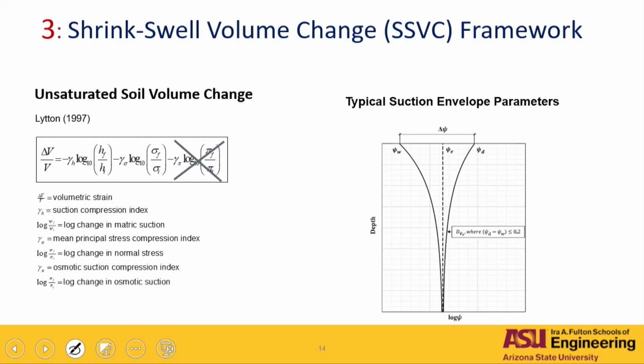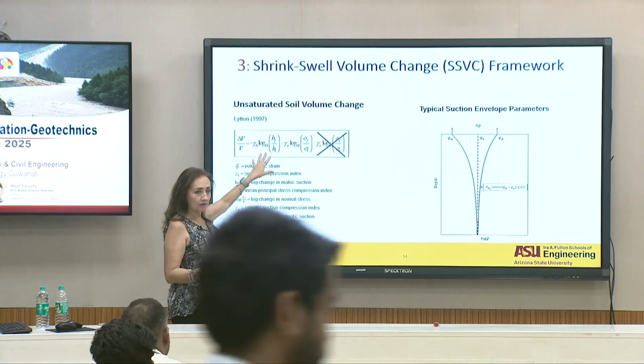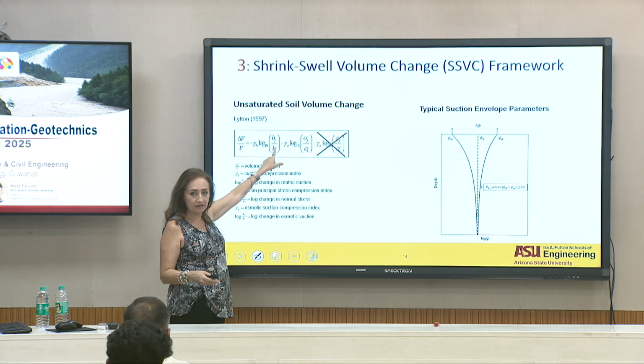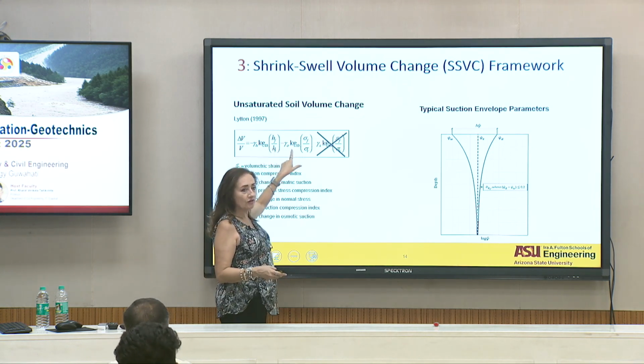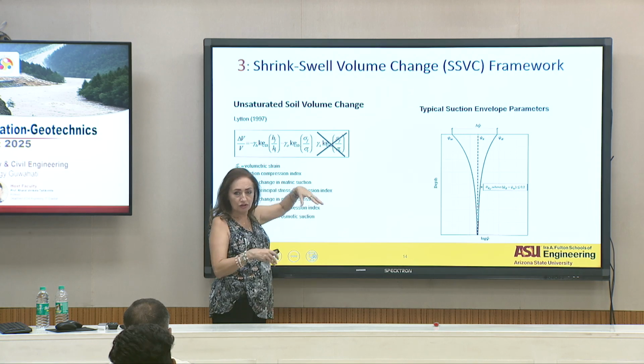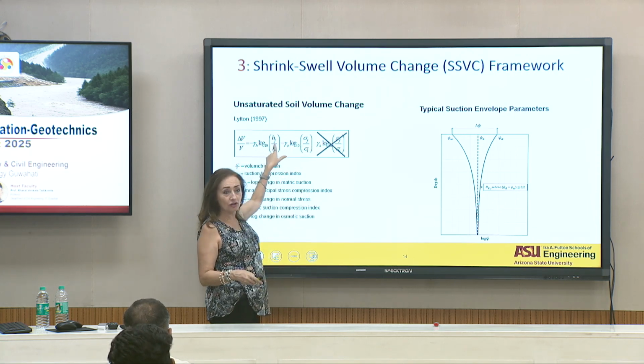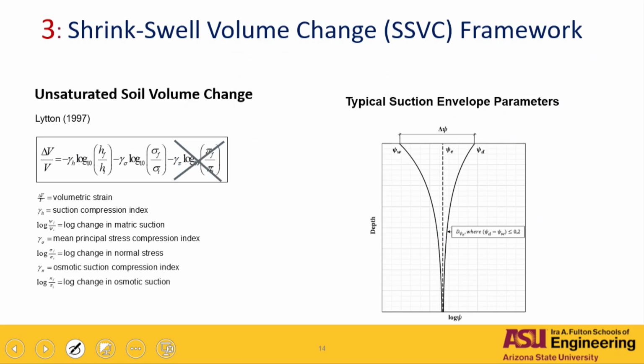So the first thing we did is, okay, we're gonna adopt a model, right, for volume change. So we adopted the Lytton model, where we said the change in volume is a summation of the change in volume with respect to the hydraulic head, plus a change in volume due to the load condition, right? So you can put the normal stress in here and the changes in suction in here, right? Or change, and then you have it.